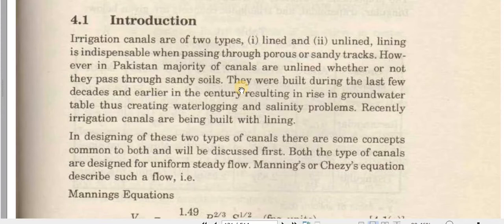If the silt is not transferred to the farmer's field, then with the passage of time the discharge carrying capacity of the canal network can be reduced. After the main canal, there is the branch canal, then major distributary, minor distributary and water course. So the main point is that a sediment transport study is very necessary in canal designing.